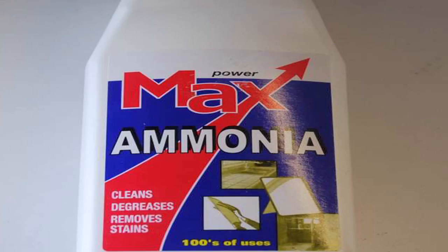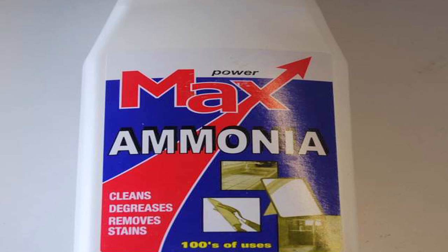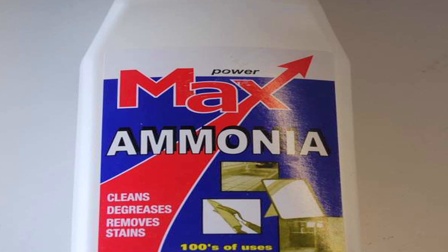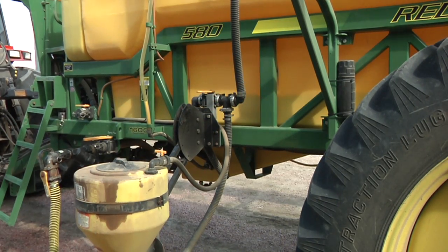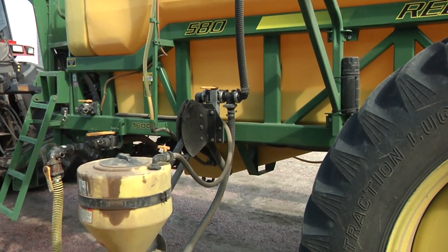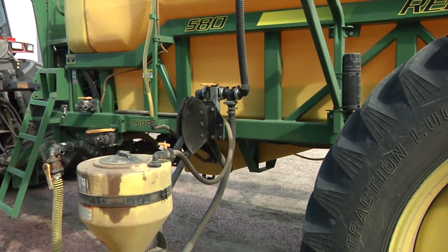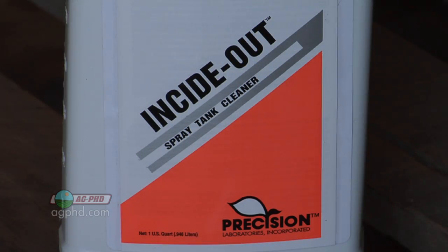When we're using a tank cleaner, we want something that'll not only pull things out of those pores and clean that residue off the sides of the tank, but it's got to be able to keep it in solution. Because let's say you use household ammonia, for example. There's a lot of guys that say, oh, I'm just going to use some household ammonia. That's fine, and it does a nice job cutting stuff off the side of the tank. The problem is when you're using household ammonia, a lot of those chemicals you're mixing with are just going to sit on the top of the tank. It's going to float on the top, kind of like oil on water. And now when you drain that tank out, well, what happens to that oily residue? It just sits right back on the side of the tank again. So you need to use a tank cleaner that's going to keep that in solution. That way when you do cut it off the sides of the tank, you can actually get it out of the tank too.